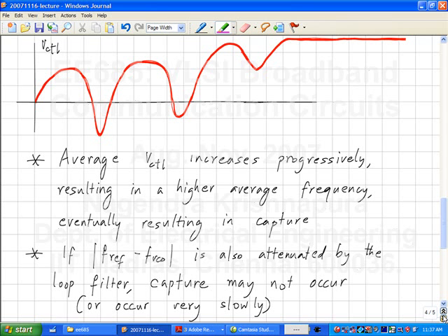No, it is moving in the correct direction, but as it reaches the peak of the difference frequency sinusoid, it also moves back in the wrong direction, right? It means that the band is getting broader and broader. So it should finally settle to the peak value. No, no, it may not, right? No, because the control voltage is the difference frequency component from the phase detector, which is a sinusoidal curve, which goes up and down, that's all.